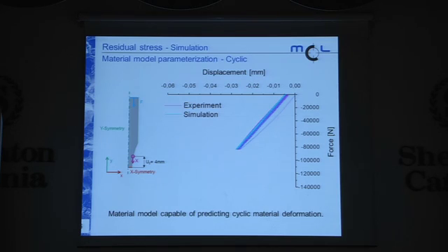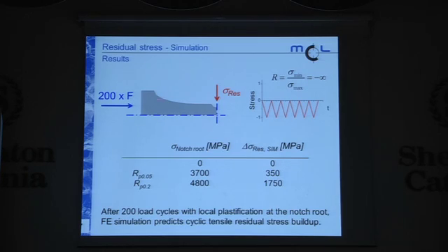And then, if you have that, you can go into your model with a certain geometry and say, apply my force 200 times. That's where hard metals generally saturate their stress response. Saturates, the residual stress buildup should be complete then. And then we saw that with a certain amount of plastification at the notch root that we provoked, say 0.05%, which is close to the measurable detection limit of plastic deformation in the experiments, we get a residual stress buildup of, say, 400 or so megapascal. And with a little more plastification, we end up with more residual stress in tension, positive values.